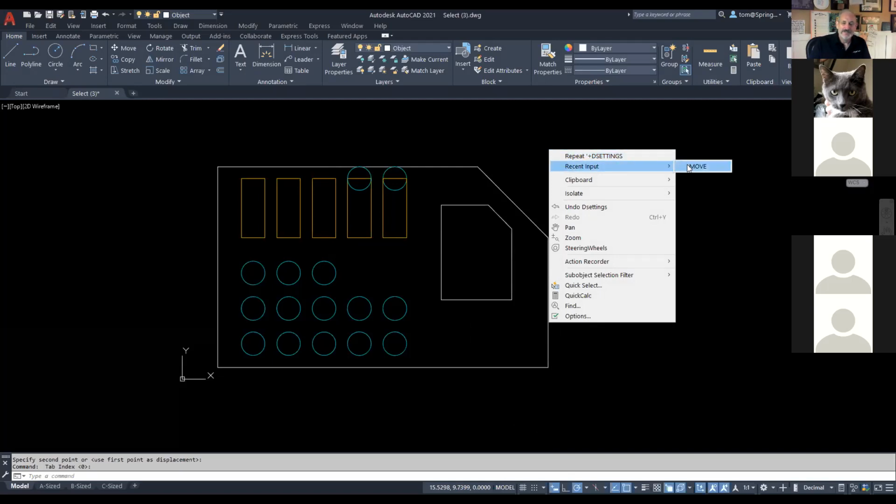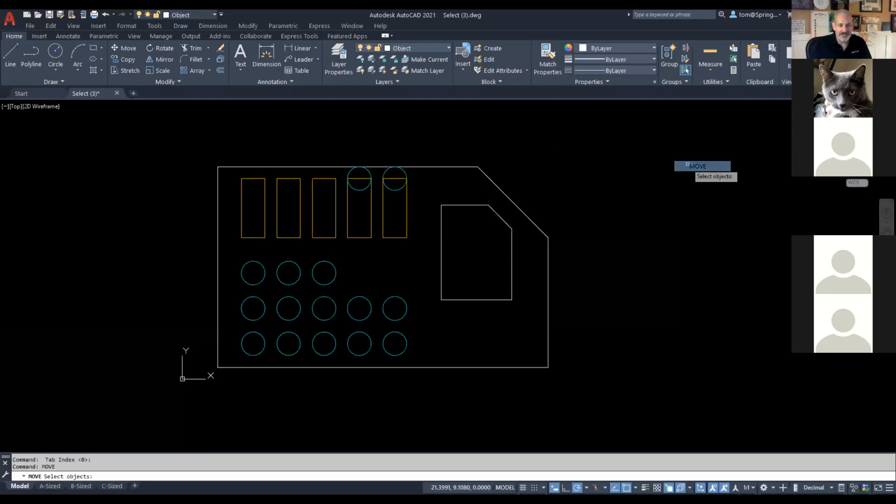So sometimes if you've done a command enter between the last 2, then you got this right here. So I'm going to right click, or I can just go ahead and click it, but you can use the shortcut. I'm going to do the same thing. Again, I click on the object. When I'm done selecting, I right click. I pick the base point, which is the center, and I drag it up to the midpoint. And I just do that for each of these.